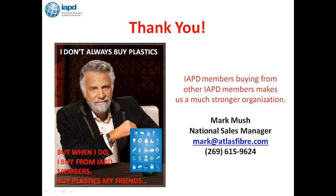The shiny skin surface that comes on the laminate sheets as they come out of the press is wonderful for printing on, very glossy. That resin is cooked against the stainless steel platens, and you get a very smooth surface. If you sand it, the ink is going to run on you a little bit. So that's another area where you have to keep that in mind.